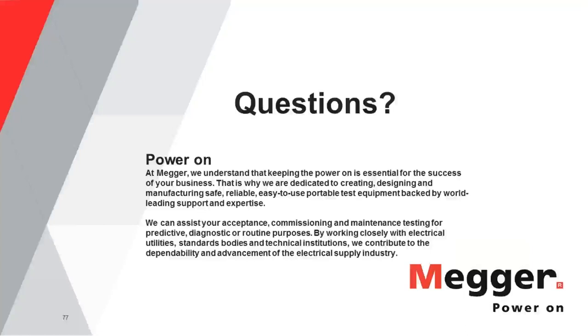Okay, I'd like to thank the person that asked that question, because that's a great question. I actually typically include that in my presentations on ground testing. Don't try to use an insulation tester. It comes up all the time. One of the reasons is a lot of times they look alike, reasonably. And so if you go to a tool crib at the beginning of a shift and you're handed your equipment, it's not at all uncommon to be given the wrong tester, and then the guy doesn't really look at it. He goes out to the job and then he's trying to use it and it doesn't work. But it's a great question.